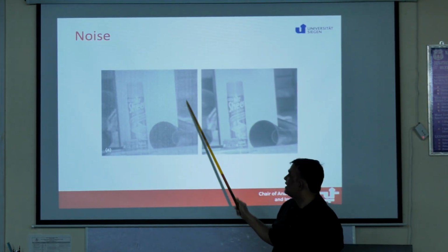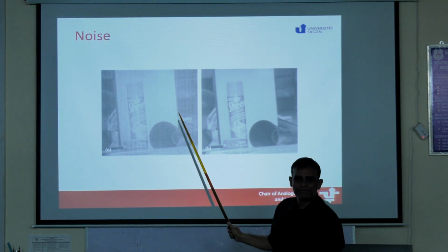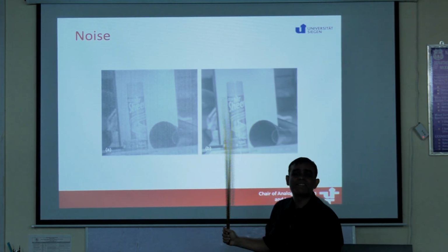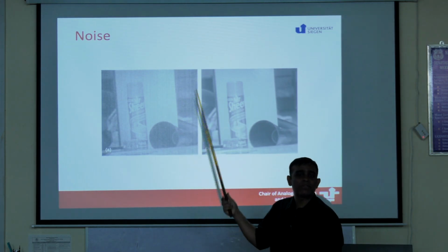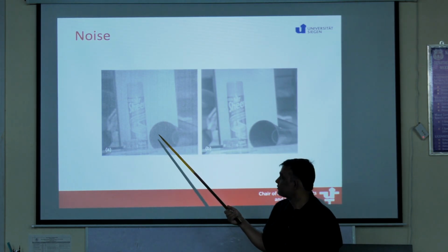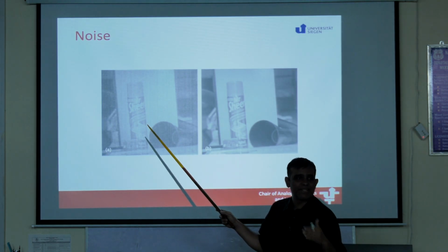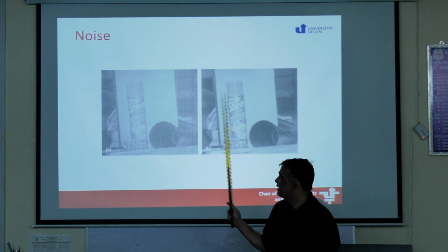So an image is captured like this, and you can see there are many ways we call this noise. One is to see there's a pattern on it. Right? There's a straight line thing. That pattern remains the same. We have to correct for that noise. It's not temporal noise, it's not changing with time, and that's why it's called a fixed pattern noise.